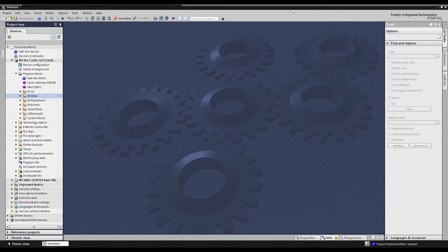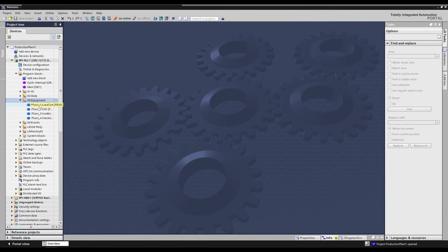The next layer is the equipment layer. This layer contains only 4 function blocks, each function block representing a specific section of the plant. In a 1500 series PLC, these individual function blocks would actually be software units, which are far more usable for such a problem because they can individually be updated and modified without needing to change any of the others. But since this feature is not available in the 1200 series PLC, I reverted back to using ordinary function blocks. So what are these exactly?